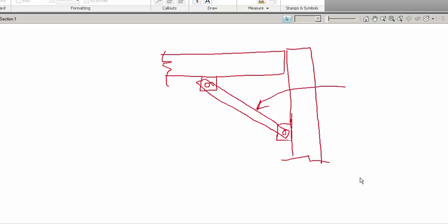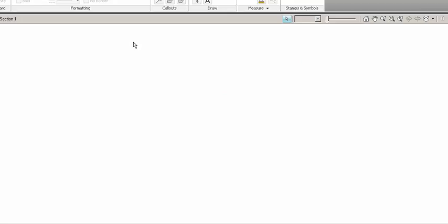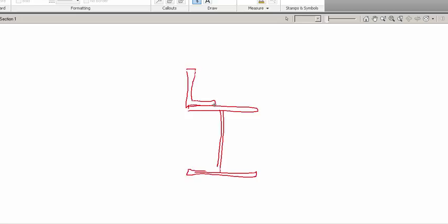They're also used for a variety of things like laying down steel decking. So for example, if you were to look at how commercial buildings with concrete floors are made, especially on the second floor, what you'll typically find is the W-beam, used in some form or fashion, holding something up, or maybe it could be open web steel joist, that kind of thing. But what they'll do is they'll take a piece of angle and put it at the end. And we're in kind of a cross-section view, by the way. And here's the steel decking. This is what it looks like in cross-section. And let's say there's some other beam over there, and they'll pour the concrete into the space.